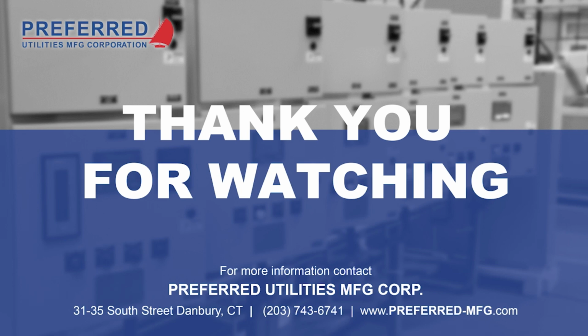So, very good question, and people will run into those issues occasionally. And it's a hard thing for the technician to diagnose because it's so counterintuitive. I'm failing a false flame because I've got too much flame signal. Really? Exactly. It's just something for technicians to be mindful of. Absolutely.